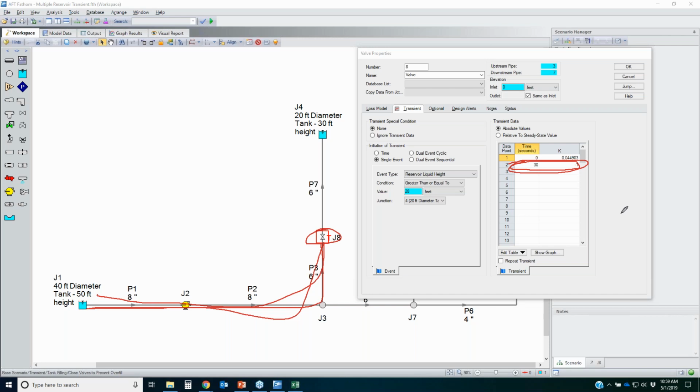So Fathom is not going to capture how the pressure surge passes through your system at thousands of feet per second when you have a sudden change like this. It's going to assume steady state behavior, and it's going to ignore the wave speed of the fluid, and it's not going to know how fast those waves pass through the system. That's what you will need Impulse for. And again, I'll go into more detail on that in one of the next webinars in the next few weeks here, so make sure that you register for that.